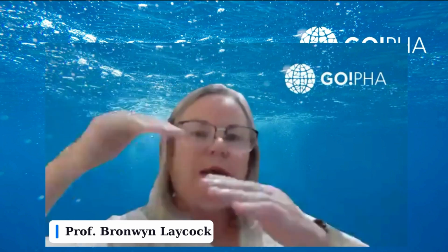Yeah. So what I was saying is that all plastics undergo transition states. If you have a plastic product, it undergoes a series of processes which can include fragmentation. It can also include conversion, depolymerization at the surface to chemical products like VFAs in the case of PHAs. But at some point, these plastic products do break apart. At a certain thinness, even PHA will fragment because it shifts across to bulk erosion when it gets very thin. So it won't always go straight to a soluble product.